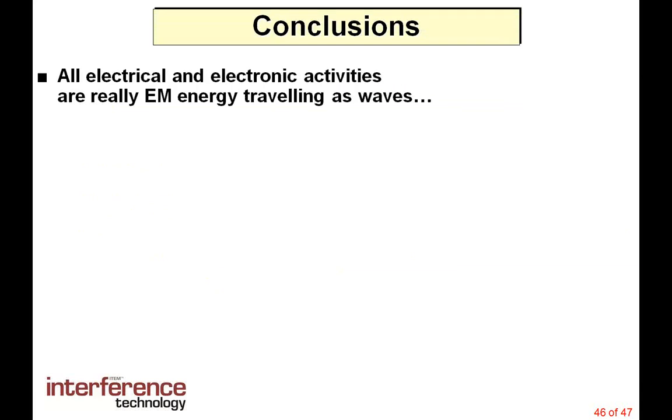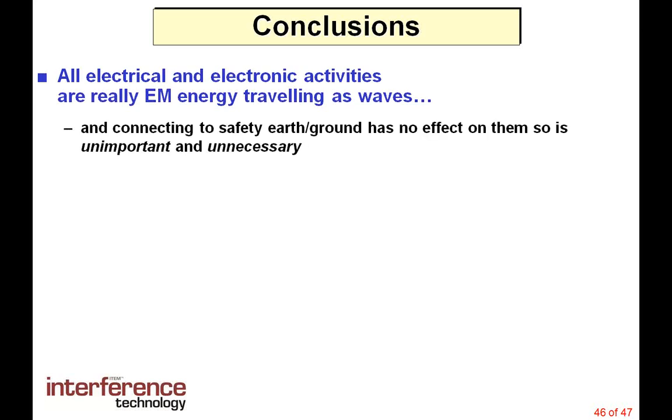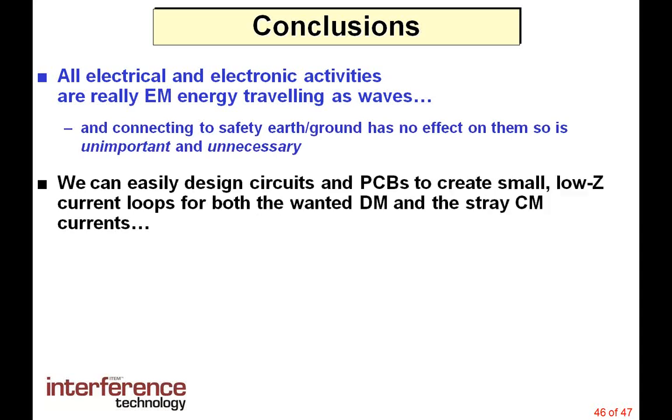So to wrap up this very brief webinar, all electrical and electronic activities, currents if you like, are really electromagnetic energy traveling as waves. Connecting them to the safety earth or ground has no effect at all, so it's unimportant and unnecessary. It may be necessary for safety, but it doesn't have much effect on the EMC. In fact, I've often removed ground connections where safety allowed me to do and improve the EMC.